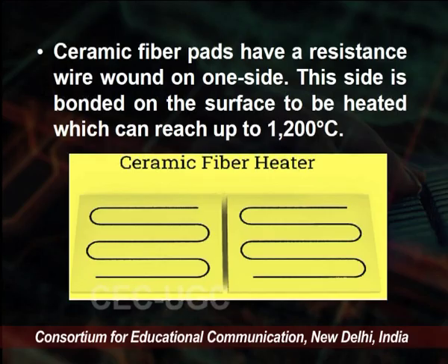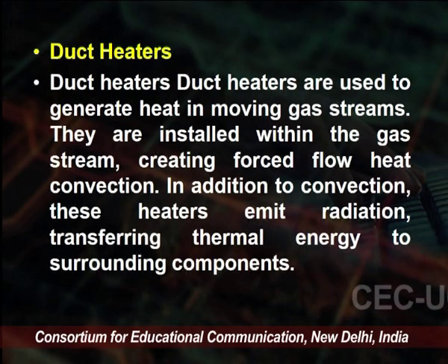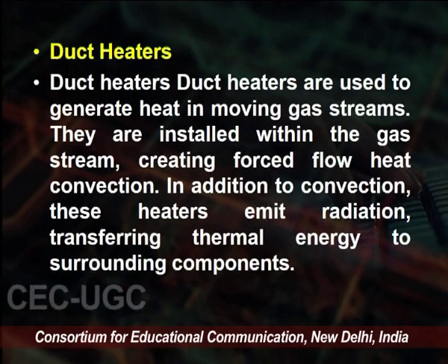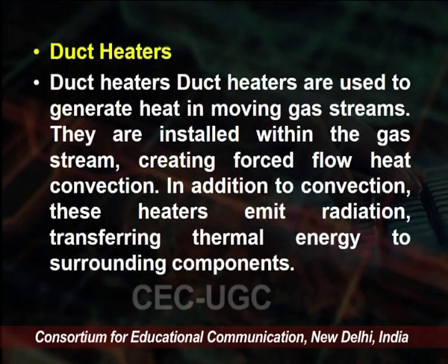Ceramic fiber pads have a resistance wire wound on one side, and this side is placed on the surface to be heated, which can reach up to 1200 degrees centigrade. Duct heaters are used to generate heat in moving gas streams.